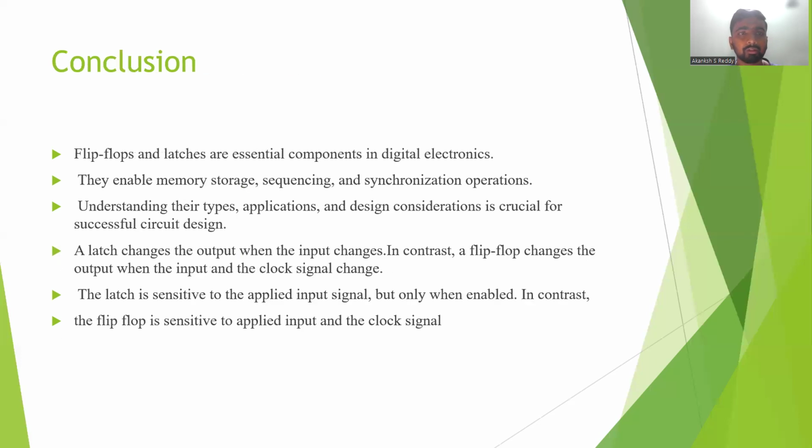And let's recap what we understood in today's presentation. Flip-flops and latches are essential components in digital electronic circuits. They enable memory storage, sequencing, and synchronization operations. Understanding their types, applications, and design considerations is crucial for successful circuit design. A latch changes the output when the input changes. In contrast, a flip-flop changes the output when the input clock signal changes. The latch is sensitive to the applied input signal when it is enabled, while the flip-flop is sensitive to the applied input and clock signal.